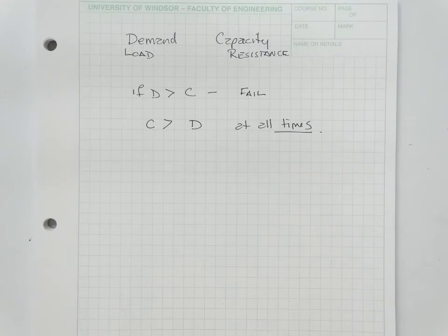Let's suppose that down below that piece of wood that I'm loading, that beam, I have a frame, a bay window. What's going to happen when that load comes on and the bay window has to deform 1.5 inches? It's going to shatter. If we put a new one in, what's going to happen? It's still going to shatter, right? There's nothing wrong with the window. The deflection is too high.